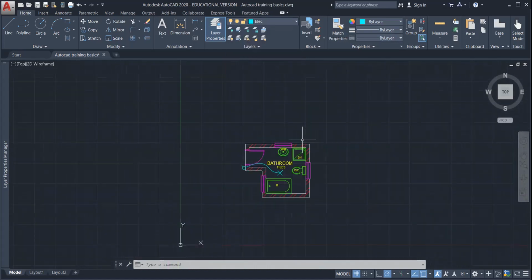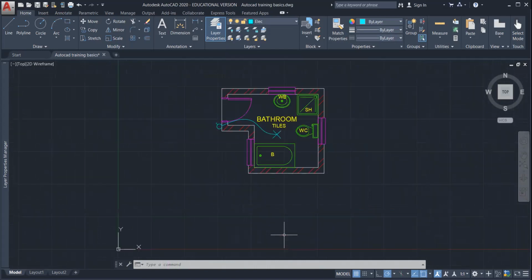I'm going to draw one elevation, but they work on the same principle. I'm going to draw it here. So you draw one to the side: copy this floor plan, rotate it by 90 degrees, and then draw it upwards. Actually, I'm going to take another view because I want to show you a door and a window, so I'm going to draw this side. But before I get there, let me first add a roof line on my floor plan.